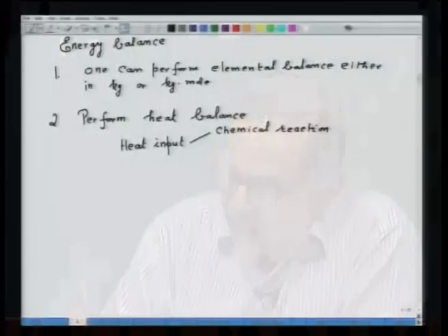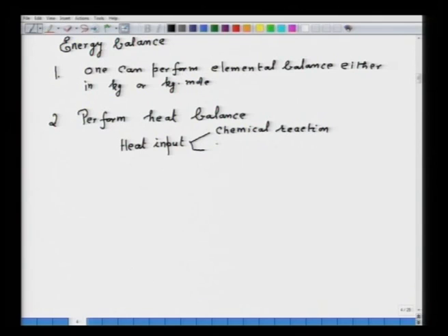Then the next step is that you collect the thermodynamic data. This is the most important step while performing the heat balance, because you have to know from where which data will be available. Though while going through the problems over here, I will give you the data, I will give you the source, but then in an unknown situation, if you are required to do heat balance, you must know how to collect the data, and if in certain cases the data may not be available, then you should be able to derive the data from basic thermodynamics. That is important.